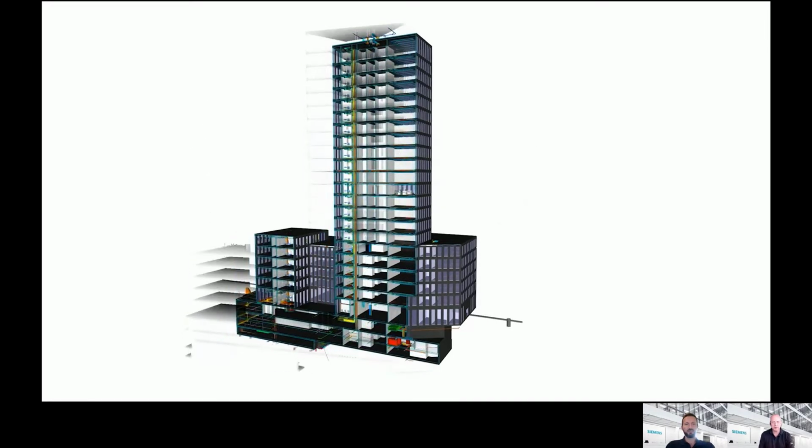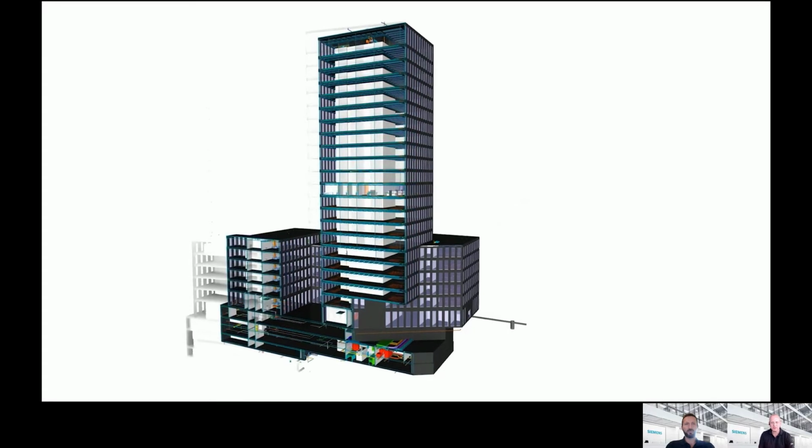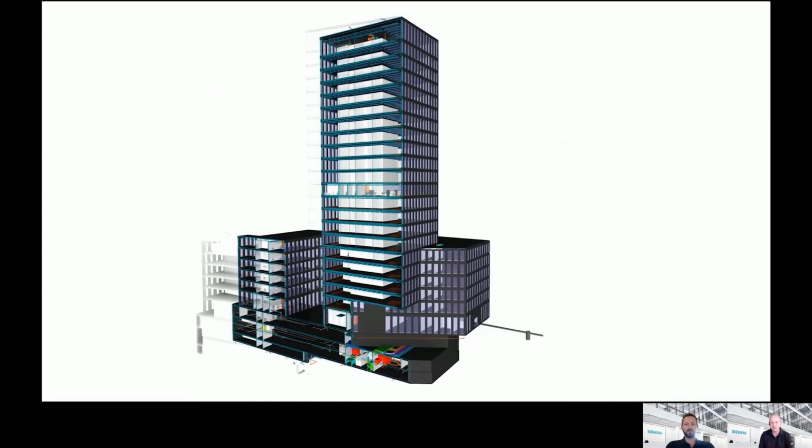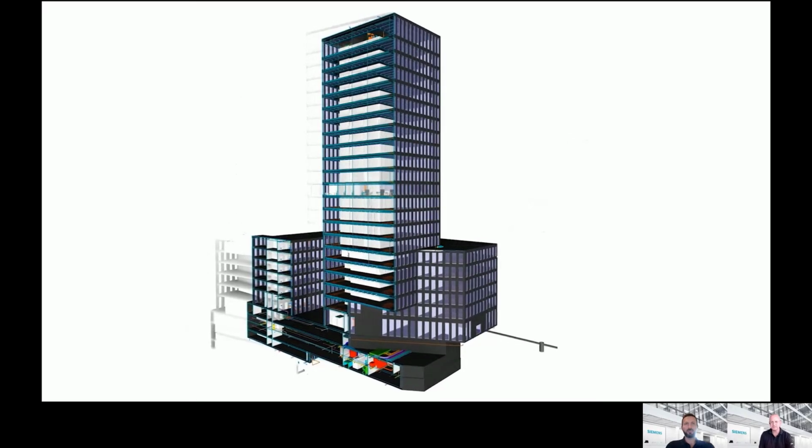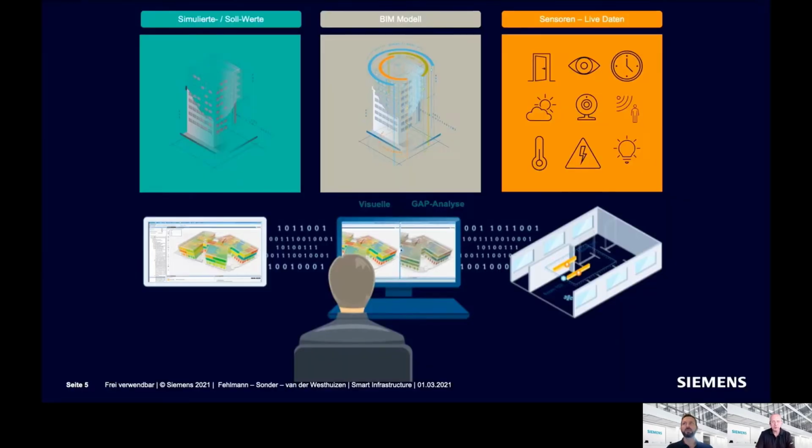The solution we came up with was to enable the client operator to identify areas where building performance optimization is required by visualizing the gap between the simulated, as-designed building performance and the real-time building performance, called performance gap analysis. Comparing actual and target values identifies the gap. This shows the system's deviation from optimum energy efficiency operations. In short, the bigger the gap, the greater the potential for optimization.